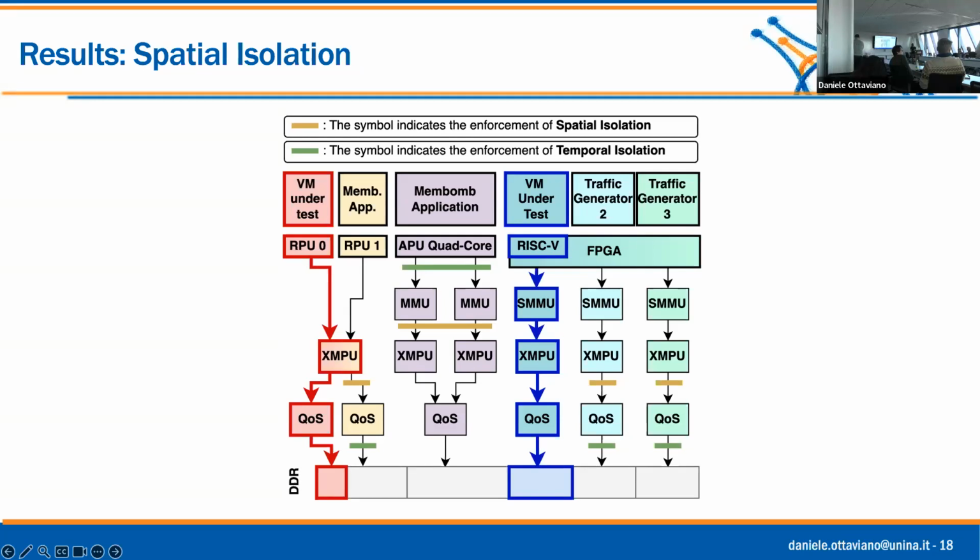No, I guess I would have thought that they would have had multi-chip systems where these more limited processors were still running. Oh, I'm sure, don't get me wrong. I'm sure there are bare-metal solutions that absolutely use this stuff. But the question is, can you point to a project that is self-consistent and being maintained, which tries to address partitioning and temporal isolation of cores, but also different ISA cores, as well as potential future cores you develop on an FPGA? That to me is the kind of problem we are spearheading. Did I summarize correctly?